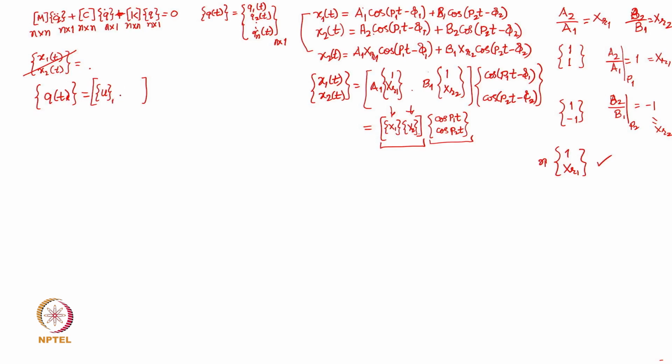If I consider this to be n degree of freedom, then u1, u2 up to un would be these mode shapes, or vectors containing the relative displacement amplitudes of each degree of freedom, multiplied by what I will call a principal coordinate or a normal coordinate, eta(t), which are nothing but these harmonic time functions.